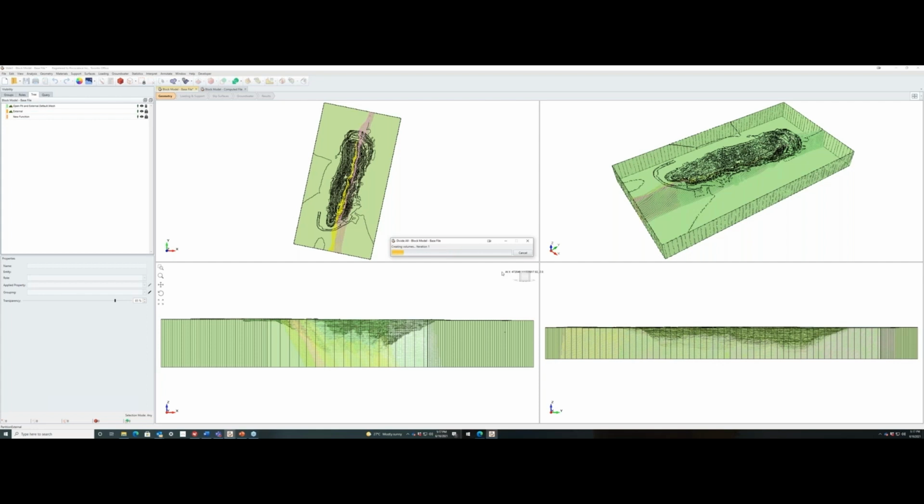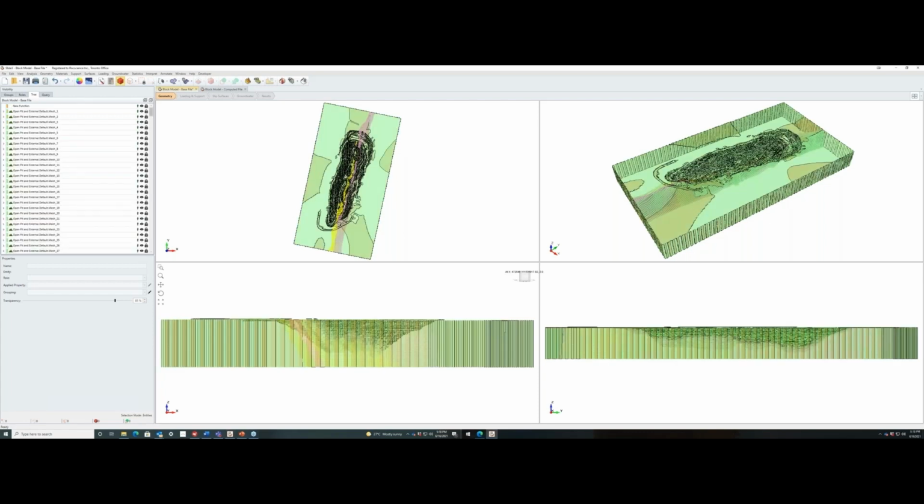But as you can see, if you have ever tried to build models using the original geometries, many times those geometries are not very nice, especially in 3D, and geological models just tend to be sometimes very complicated. Cleanup alone can take you sometimes several hours through no fault of the program. Everybody who has done 3D geological modeling will be very conversant with these problems. So whenever you can use the block model, you can save yourself a fair bit of time, at least as a first iteration to looking at the stability of your pits.